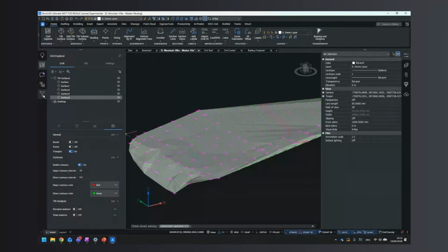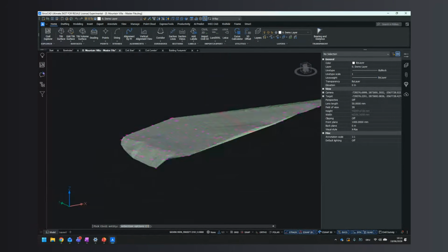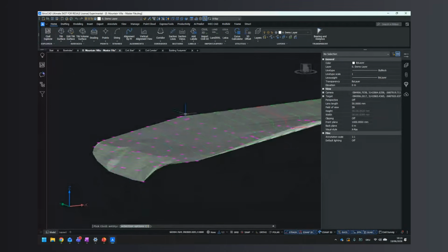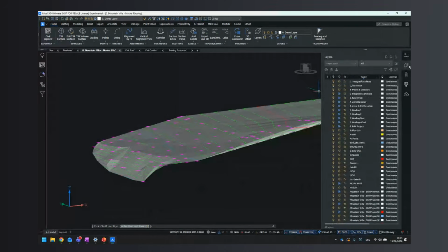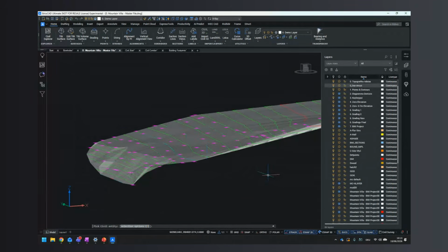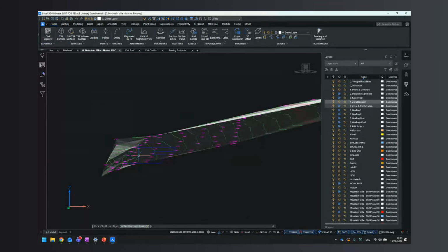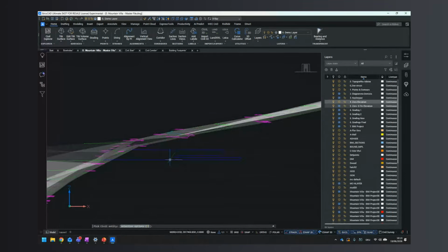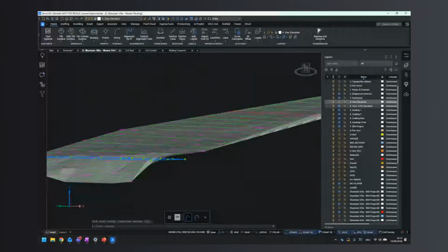So we have a thin surface. So what do we need to do? We need to create a building. We need to do excavations. So what I did prior to this presentation is insert the building plans and find what the 0 elevation of the building should be. So with the form of this polyline, this indicates where the foundation will be.